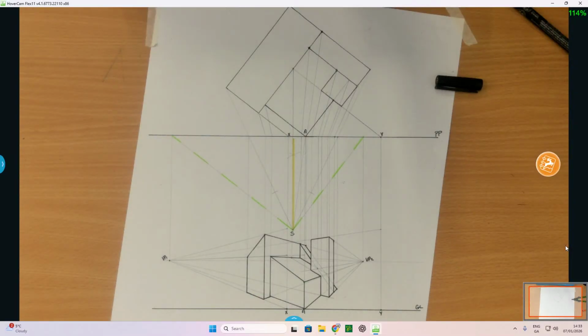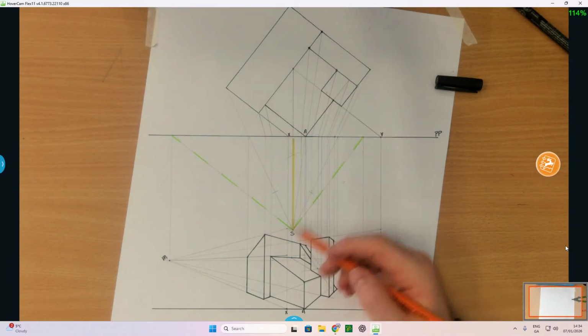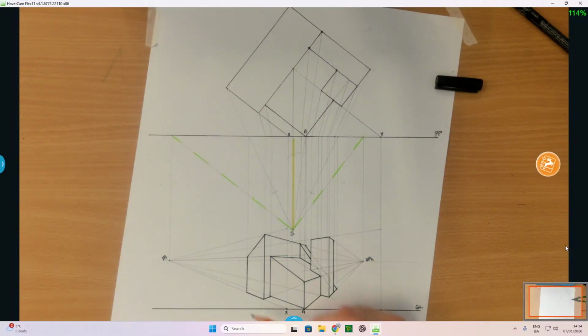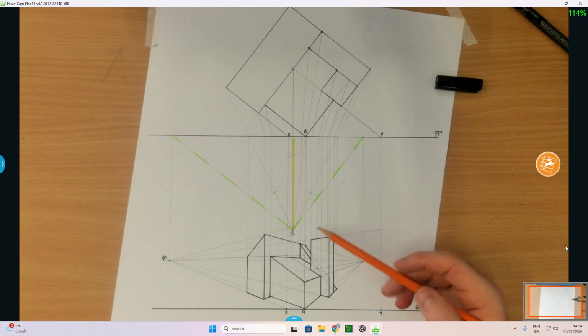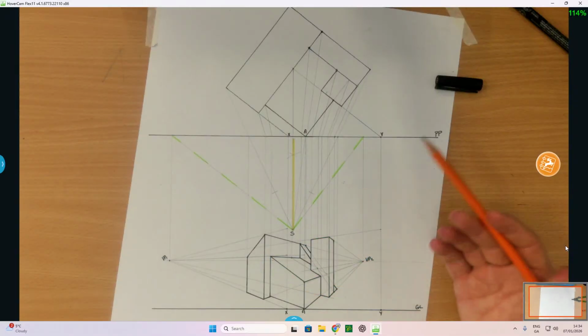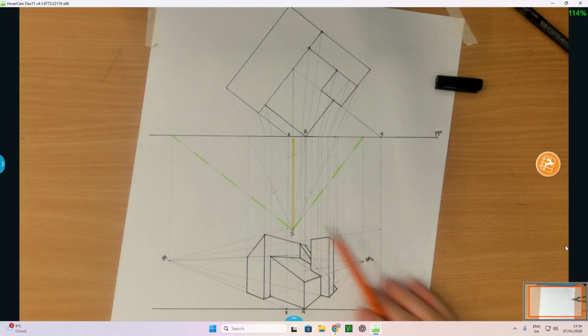Okay, so you have it, folks. That there is a perspective question. Nice little challenging problem where we had to use height lines to help us determine sloping surfaces. At higher level, the only difference is that you would be getting a slope surface by using what's known as an auxiliary vanishing point, which actually sometimes is a little bit easier than using those things.